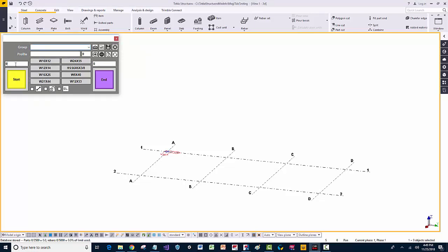of the base defaults. Let's say we're going to start by setting up our columns on the project. Here I'm going to set the bottom of base plate elevation or top of footing elevation as -2 foot as an example, and let's say the top of our roof steel or the top of our columns are going to be 20 feet.